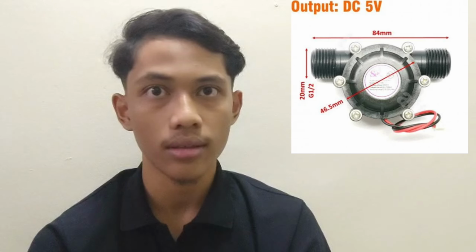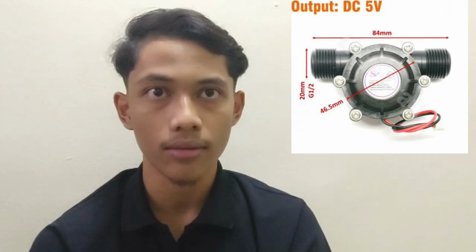The second part is the penstock. A penstock is a pressurized pipe that guides water to the turbine. And this is the penstock that I bought. The third is the turbine. It converts the energy of falling water into rotational motion. And these are the several turbines that I researched. The fourth is the generator. A generator transforms mechanical rotation into electrical power, and these are several generators that you can buy and that I researched.